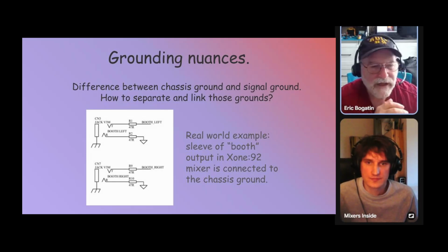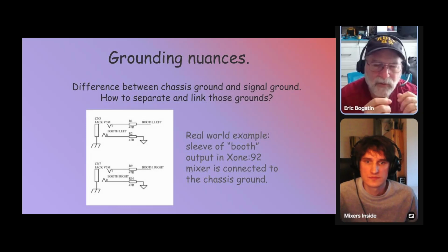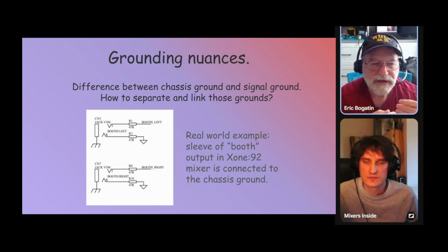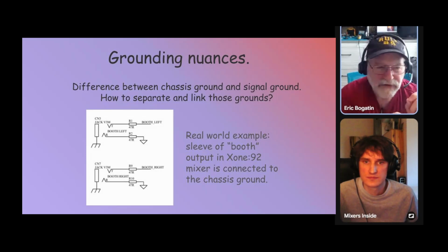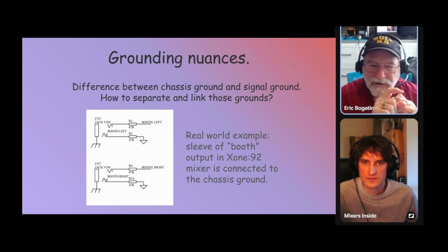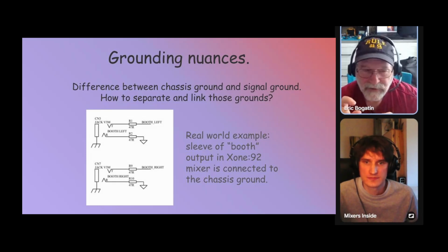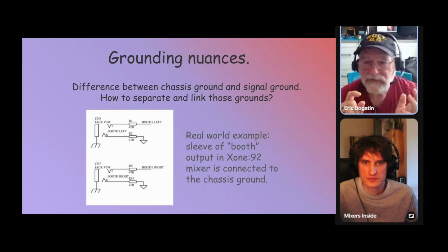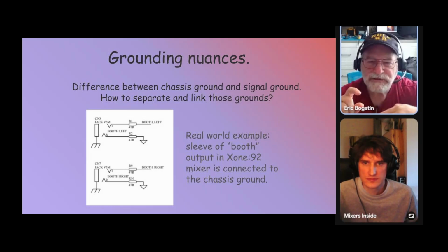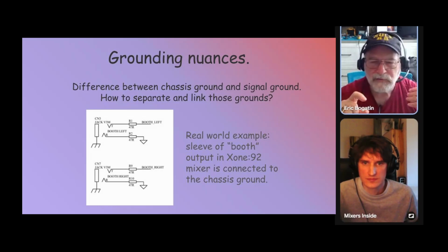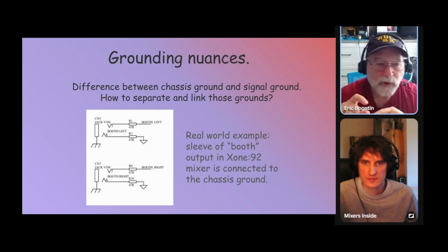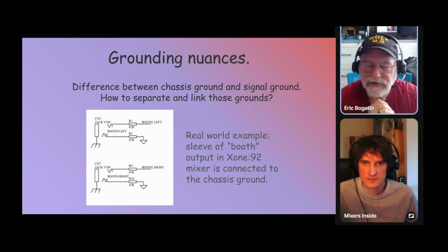That's the low side. When you plug it into the chassis and you have a wire coming from inside the box, from the signal line, if you now also connect a wire to the chassis at that point, you're going to have two wires, the signal and the low side, the chassis connection. If you connect a preamp and you look at that voltage, perfectly fine. If the chassis voltage goes up and down relative to the outside world, earth ground, both of them are going to go up and down the same. The voltage difference is perfectly fine.